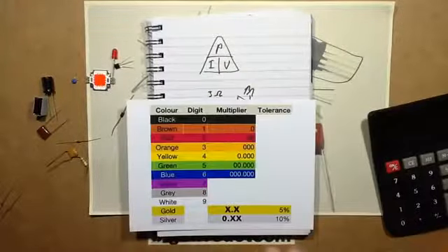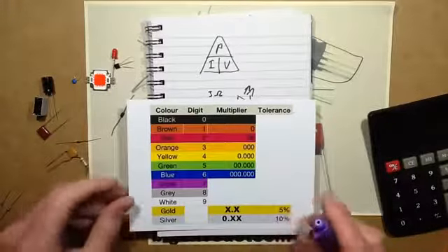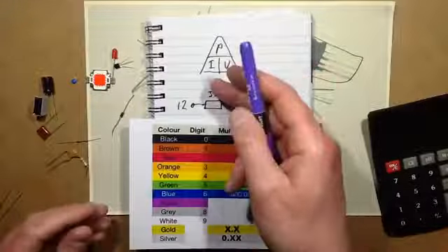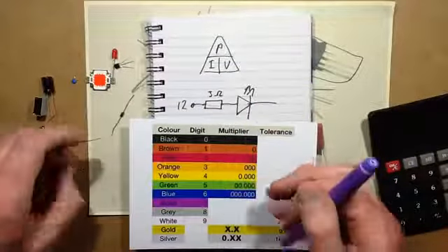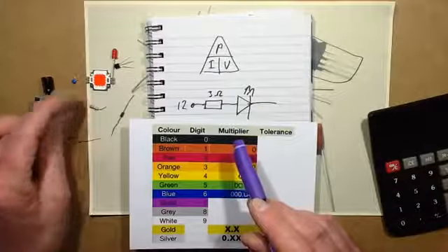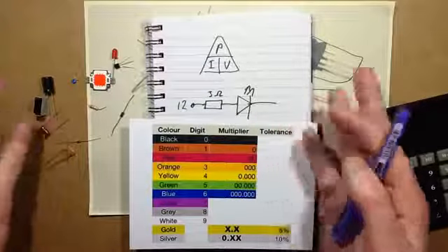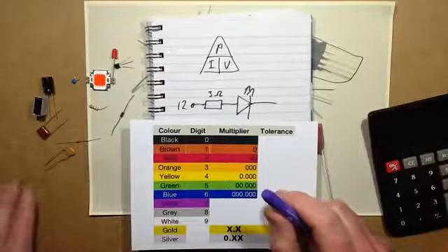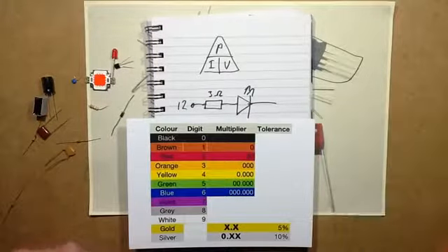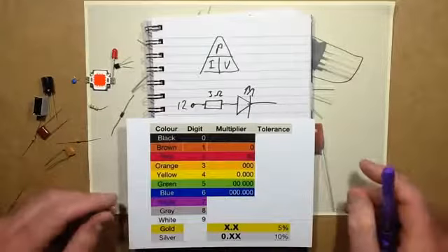That's just a summary. I'm not going to go into too much detail because it would get boring very, very quickly. But this is just the basics of what you need to know: how to work out the power rating of a resistor if you're driving quite a heavy load with it. In most instances, a standard quarter-watt resistor is fine, and how to choose the resistance value to limit current to whatever you want through LEDs and things like that. So fundamentally, that's it. Hopefully that's helped, and I've not overcomplicated it as I sometimes do.